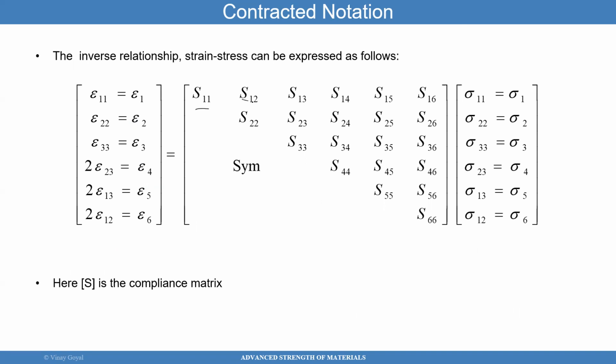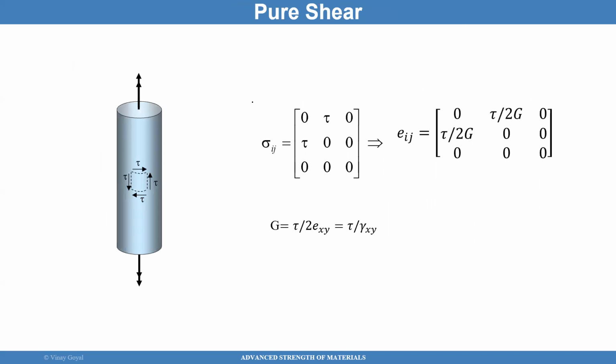So let's start with a very simple test. But I'm going to cover pure shear first, okay? If I apply torsion only, just torsion here, what people have found is that you actually, by doing that, and if I take a little square, what you find is that you get only pure shear. You get nothing more than just shear. So there's no normal stresses, nothing. This causes this square here, and that makes sense, you can imagine. It's going to make that square distort and shear. If I apply a shear like that, you expect it to distort like that. It makes sense that you should do that.